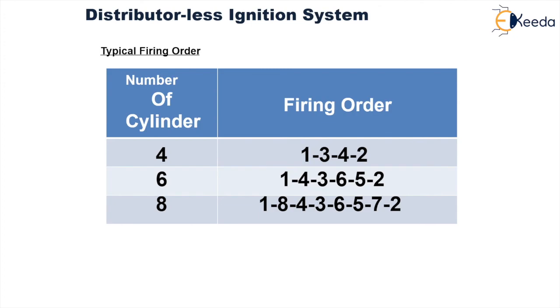All these pistons, along with their connecting rods, in case of a four cylinder inline engine that we have considered, are connected to the single crankshaft. If the subsequent cylinders are sequentially fired, then the individual region of the crankshaft will be subjected to very high loads as far as the pressure is concerned and also as far as the heat is concerned. This will lead to the failure of crankshaft. Hence, in order to avoid this, the firing order is thus maintained as we are seeing in the table for different number of cylinder arrangements.